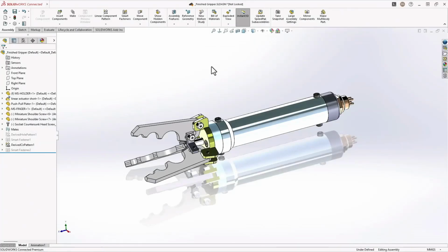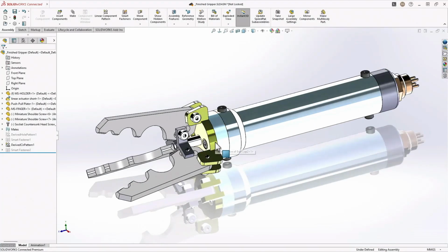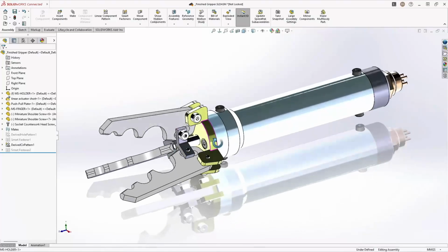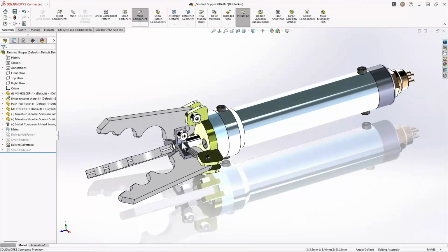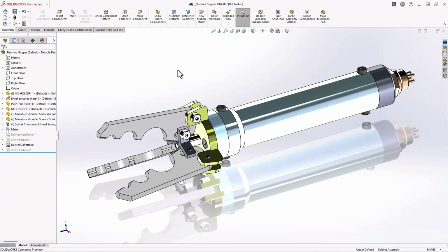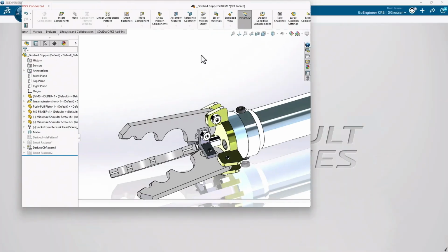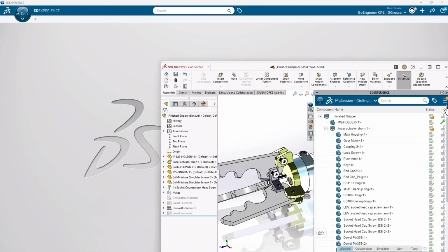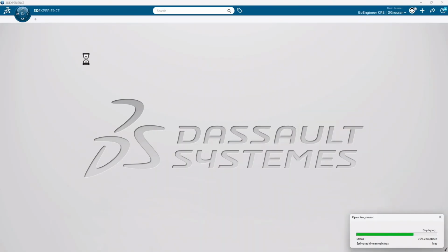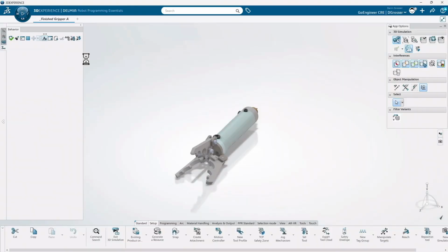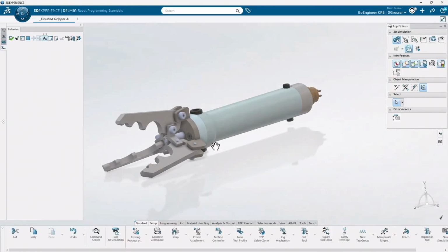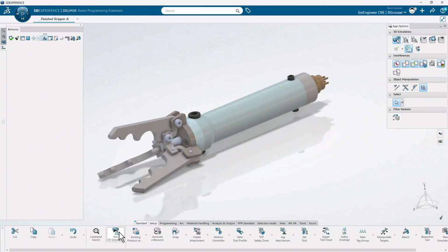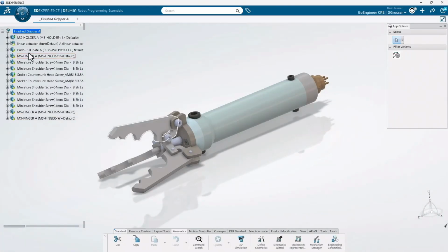Now, this being SolidWorks data, once again, it's something that we create, we parameterize, of course, in SolidWorks, and then we put mates on it. And the mate thing, that's great. But the mates are made by a little processor called D-Cubed, and it's baked into SolidWorks. And it's not something that translates in any file type, essentially. It is a unique thing to SolidWorks. Here, we're just dragging and dropping directly from the SolidWorks interface into Robot Programmer. Now, the bodies come in. It comes in as a full component, so the assembly structure is there, of course, as you would assume. But it doesn't have the joints and the mates and those types of things. That is something that you can define.